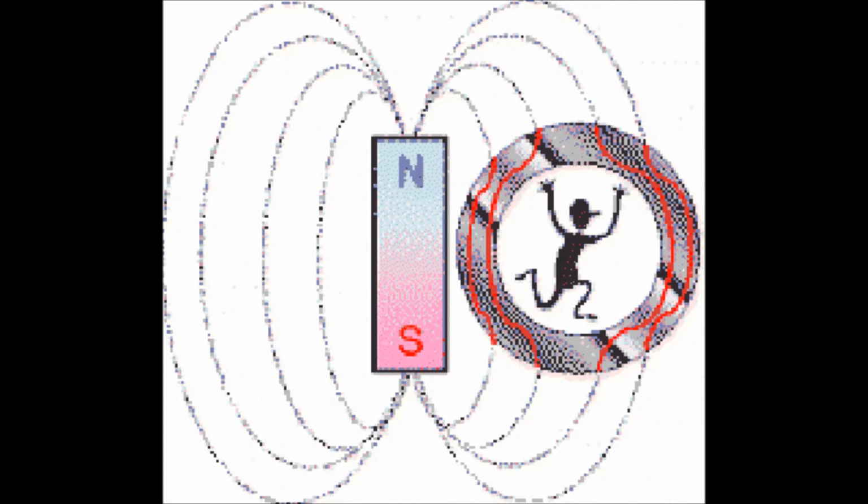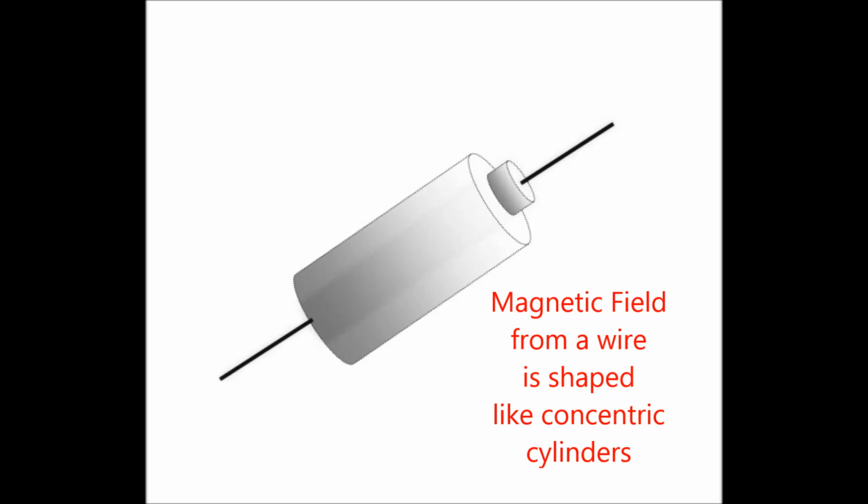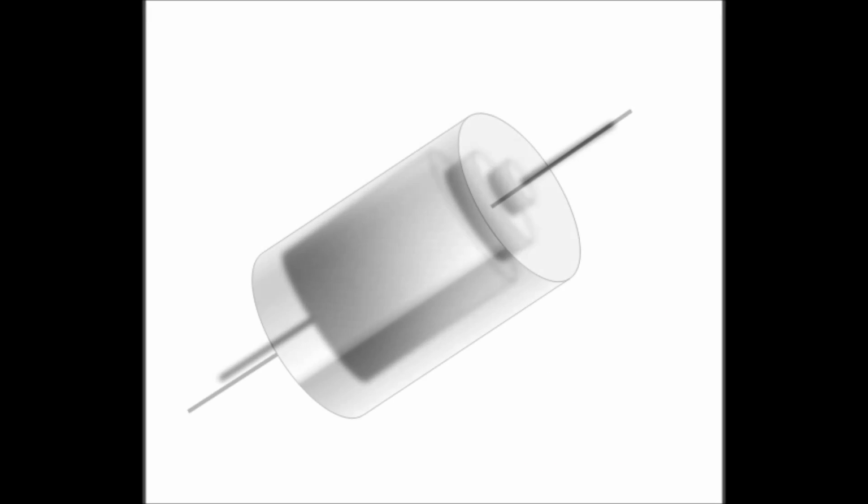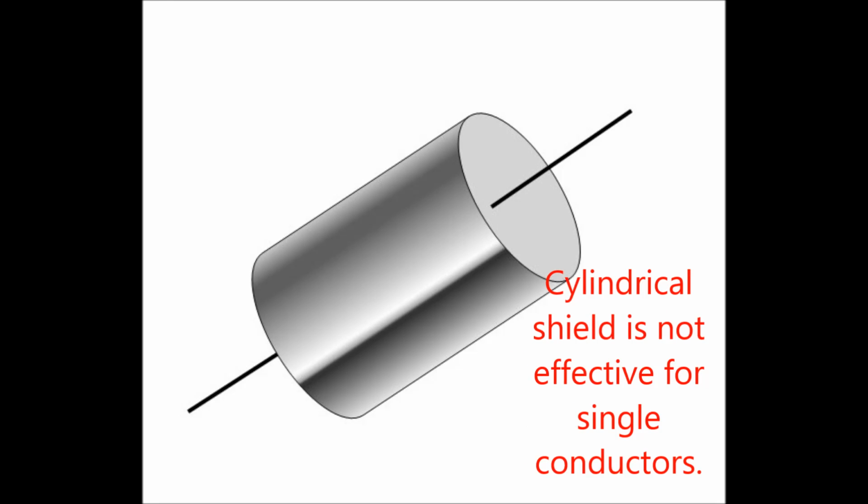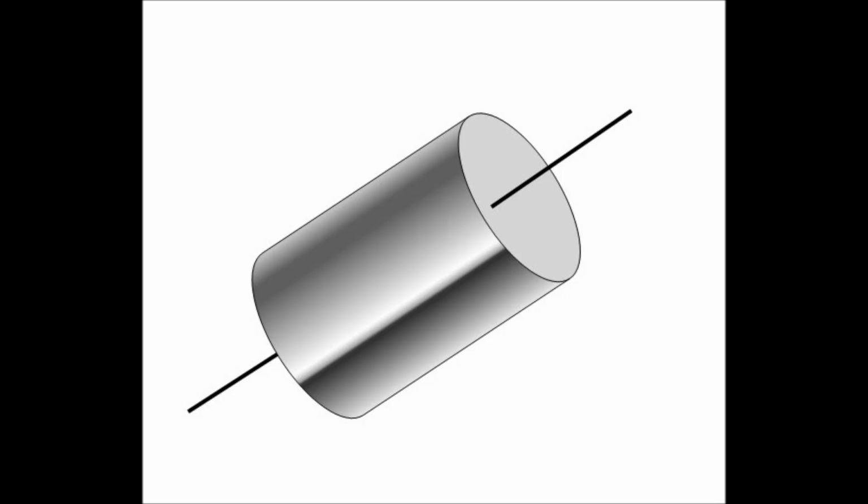Note also how magnetic field is concentrated at the edge of the shield. Gauss meter readings at these edges will be higher than if no shield was present. Shield design should take into account the position of these edges. In general, spherical and cylindrical shaped shields around the area you want to protect work best. This is because magnetic field lines resist making sharp turns. When spherical and cylindrical shapes are not possible, it is always best to make bends with a curve rather than a sharp crease. Note, however, that a cylindrical shield around a straight line conductor wire does not prevent the magnetic field from emitting. It will, however, protect the wire inside from fields originating outside the shield.